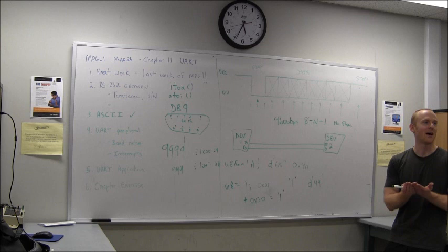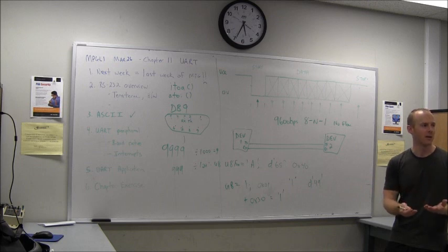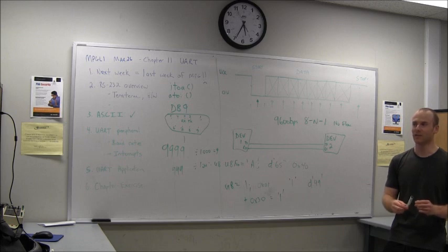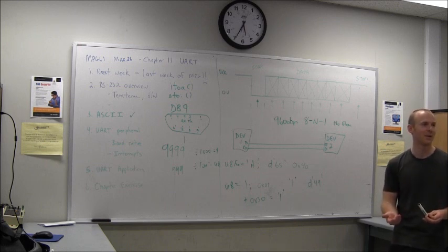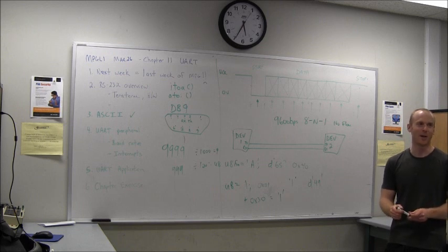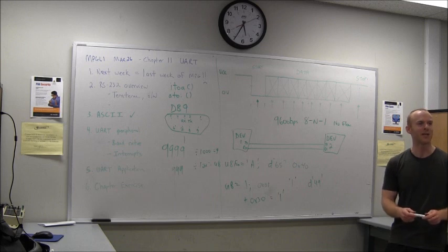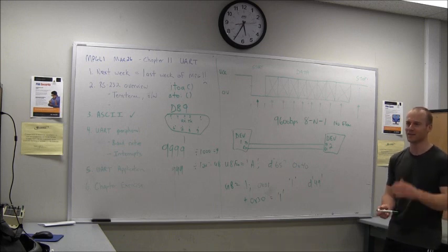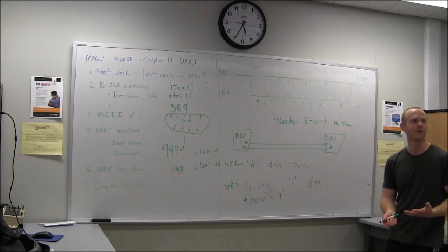There's a couple of registers that allow you to do that, and sometimes you can get it bang on. For 9600 you can't. There's going to be a wee bit of an error in there, but you can get close enough. Okay. So for this processor, it's kind of a crappy UART baud rate generator, and you end up with an iterative process to get the right register settings. Iterative processes are bad. Iterative processes demand spreadsheets. So I built you a spreadsheet. There's a baud rate calculation spreadsheet, and part of the exercise through the notes is to use the spreadsheet to get the numbers to generate the baud rate. You'll see about it when you read it.